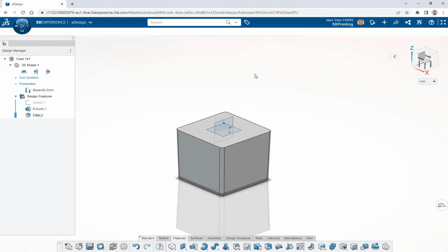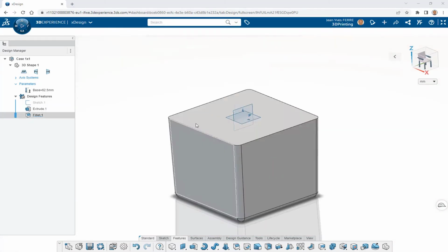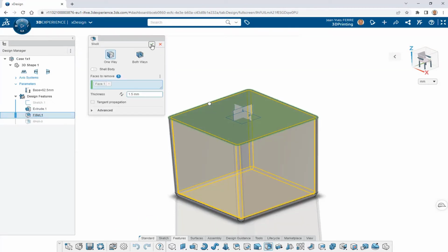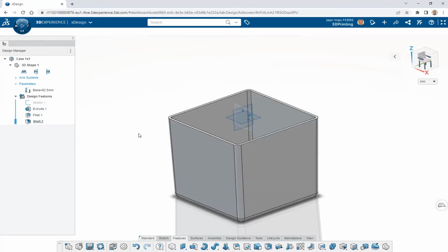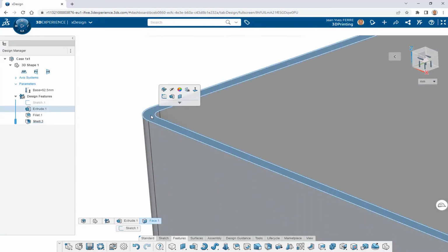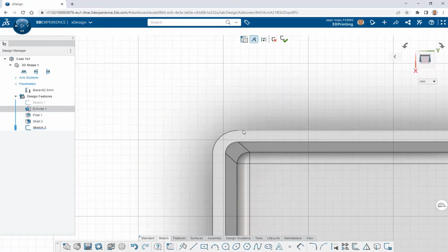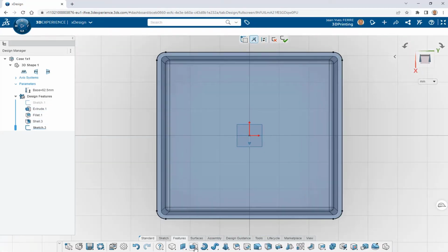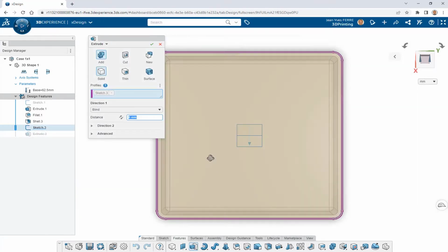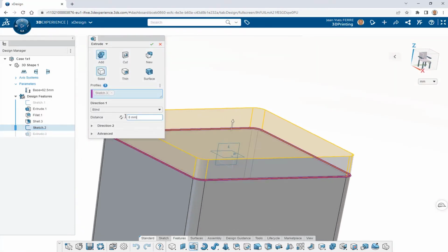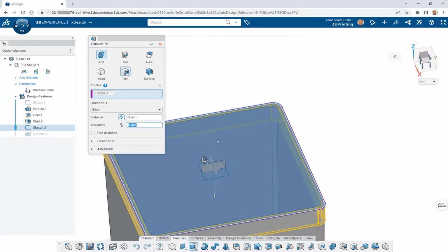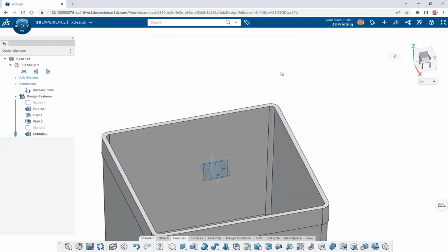It's a box, so I shell it with 1.5 mm thickness and I add a rim to reinforce this box. To do that, I select top face as sketch plane and select one edge. Then click on Select Tangency to get the full loop and convert edges in my sketch. This will be the geometry for the rim. Then this is very easy with the same extrusion tool as before to select direction and just extrude as a small thickness because of course a closed box is useless.